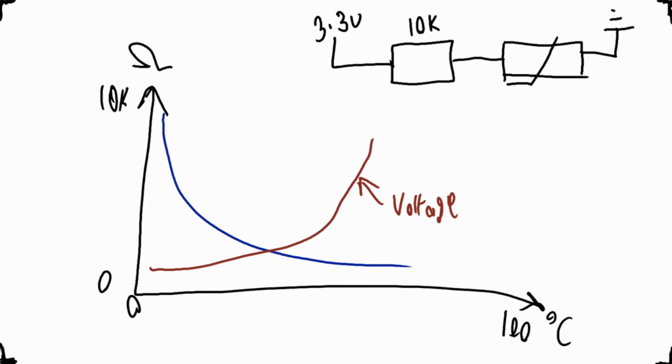Thankfully, if you have the circuit set up correctly, we also have the LM35 on the Arduino circuit. The LM35 is an adequate temperature sensor. In this experiment, we're using the LM35 as our good temperature. We can take that as the temperature that the room actually is, and we trust that value.